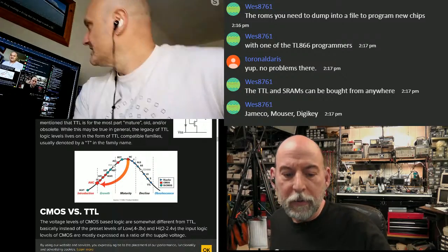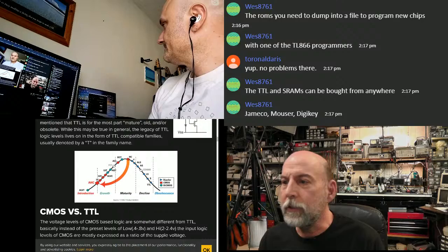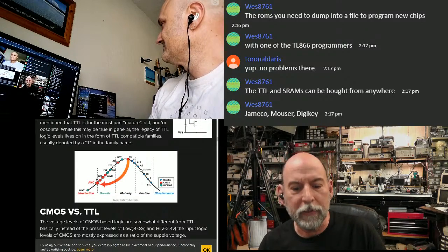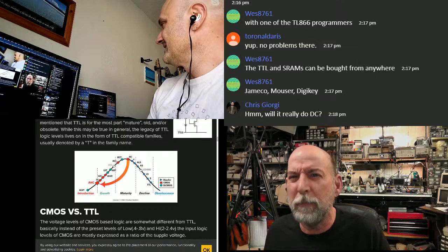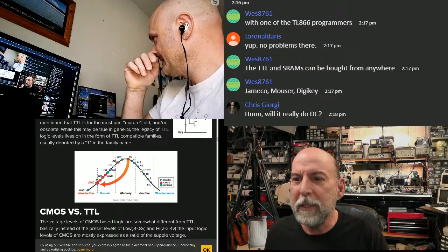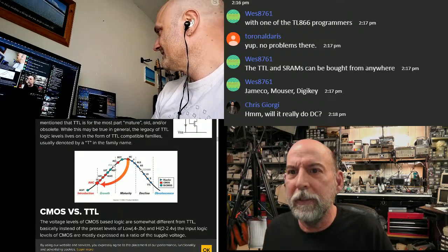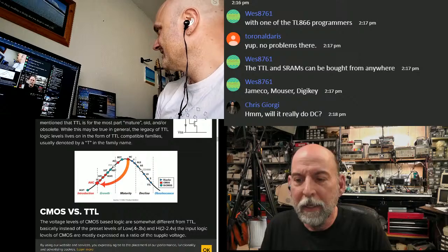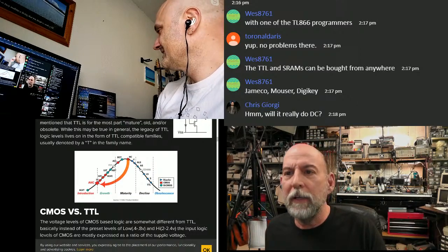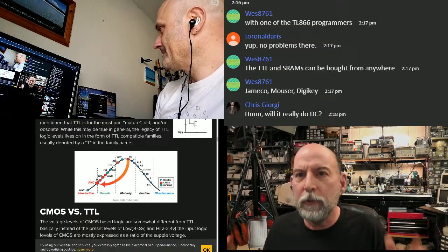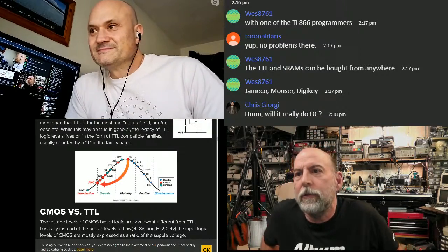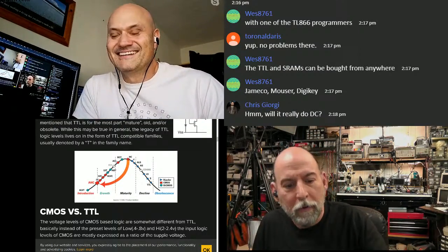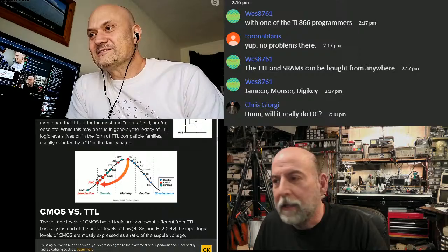In one of the other articles, I talk about the math that you just spoke about, how 8 bits actually comes out to be about 63 dB signal to noise, somewhere in there. And by the time you get to 9 and 10 bits, you get to around 80 dB, which is the limit of a lot of analog amplifiers. So people that go, oh, I have a 24-bit system. Yeah, but only the bottom 11, 12 bits are useful. Yeah, so it's often the case.